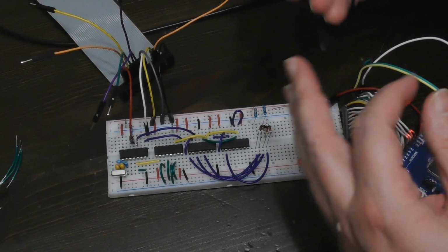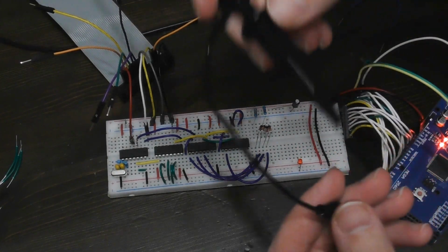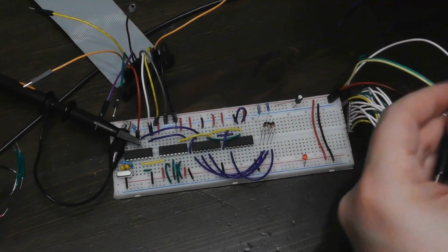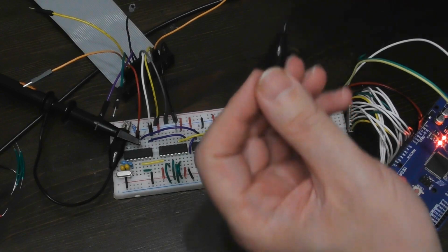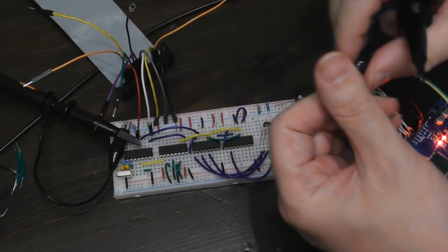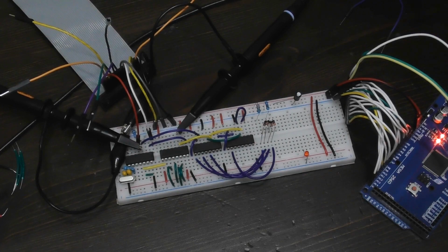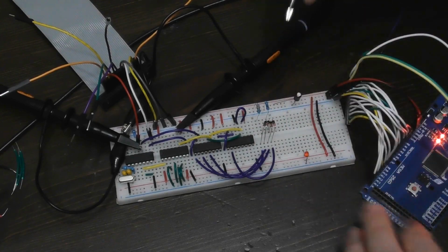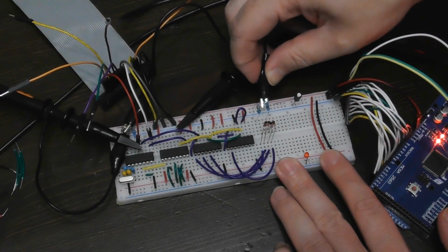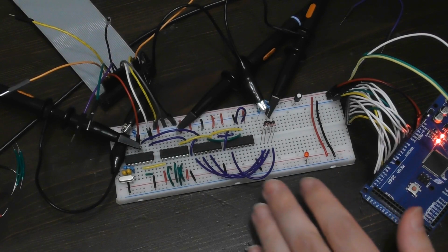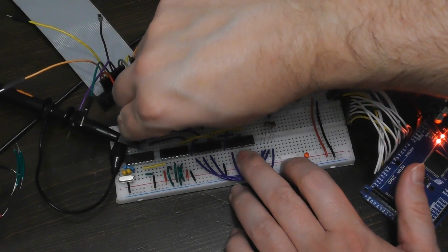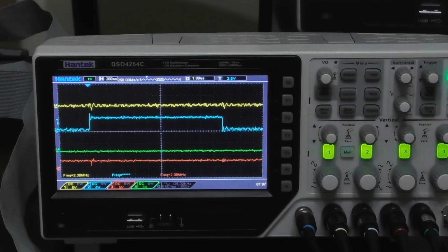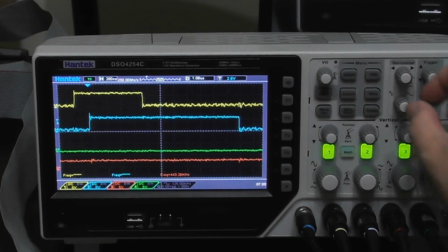So what do I want to put on the scope? I'm definitely going to want to see the signal coming off the floppy disk drive, so I'll put that on channel 1. Let's put my clock signal in as well, just to see how this all lines up with that. And other than that, the main thing I want to probe is this new signal that I've just added there. So let's measure the voltage across this resistor. And I'm going to start the disc spinning. So there's that on the scope.